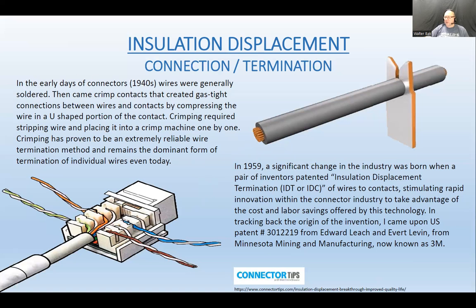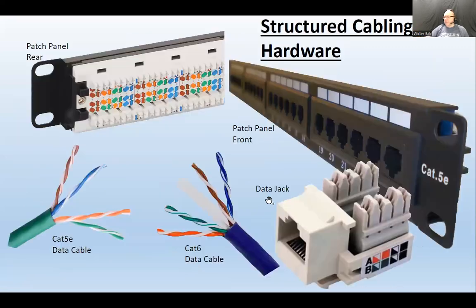The other one I was talking about was a plug. Okay. Jacks like this are designed for solid cables only. And we're going to terminate both. We already have started lab 2 with some groups. So that will be insulation displacement connector for the modular plug. And we are using the solid core wiring, and we're using the solid core jacks or the plugs that are designed to handle solid core wiring. Right?